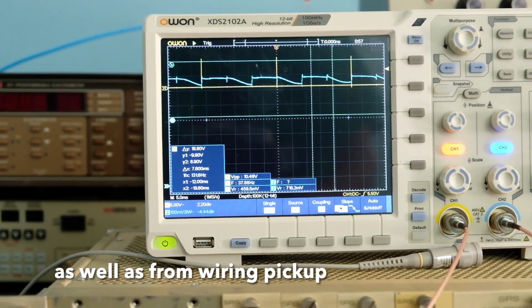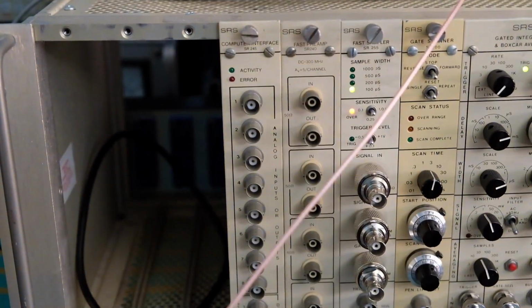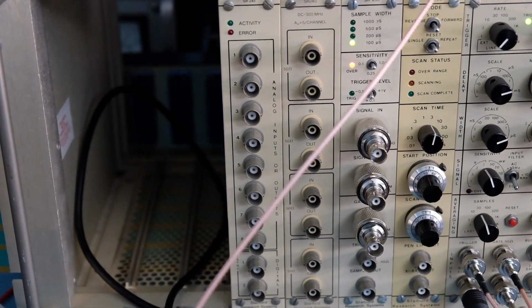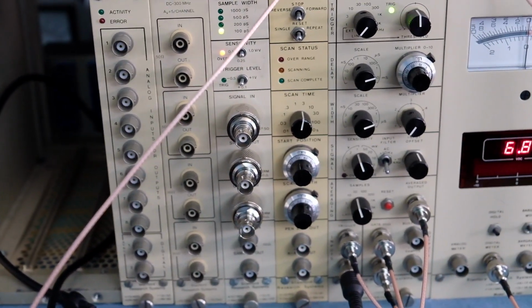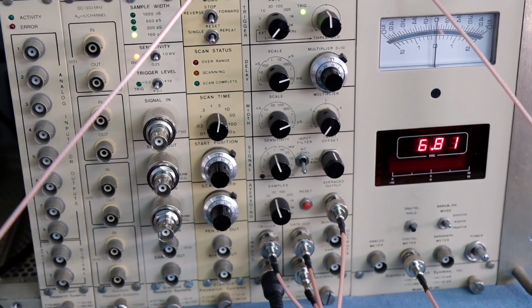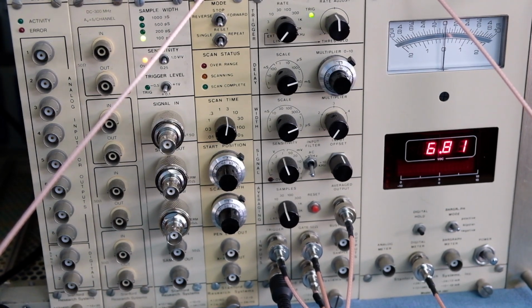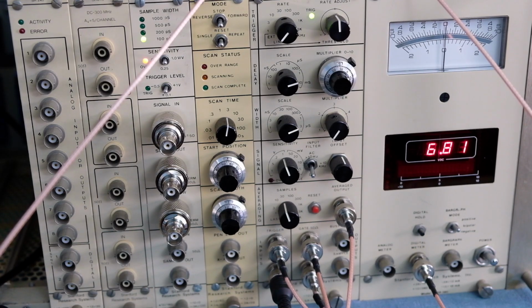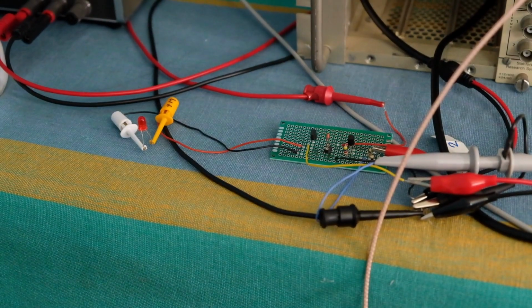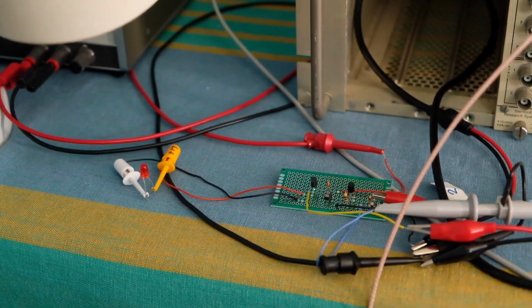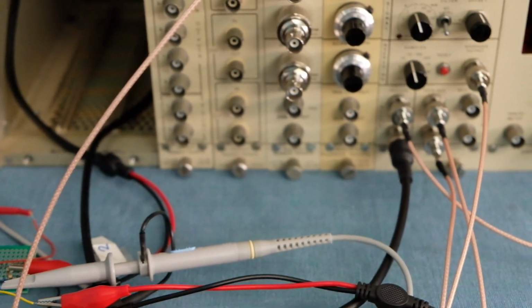So the idea of this experiment is to show that the boxcar integrator can reject any noise that is uncorrelated with this trigger. In this case, I put the trigger at 8.8 milliseconds, which is totally unrelated to the 60 Hertz mains frequency noise that may be either electrical or optically being coupled into the LED. So we'll take a look at where I'm positioning the trigger.